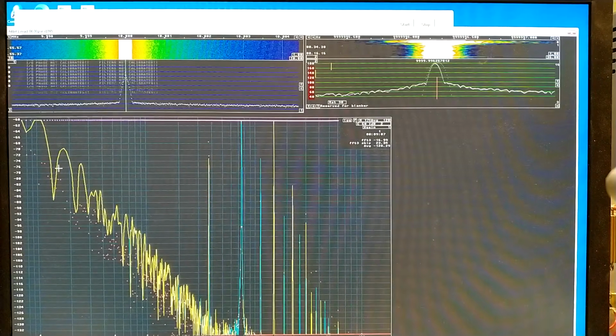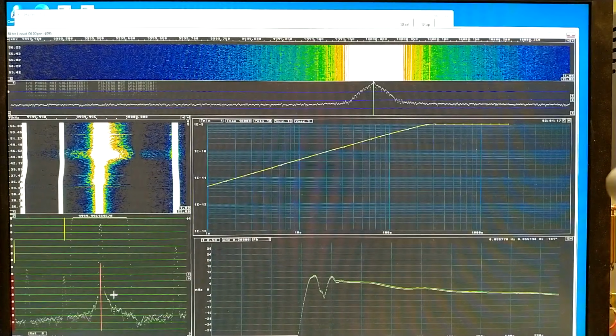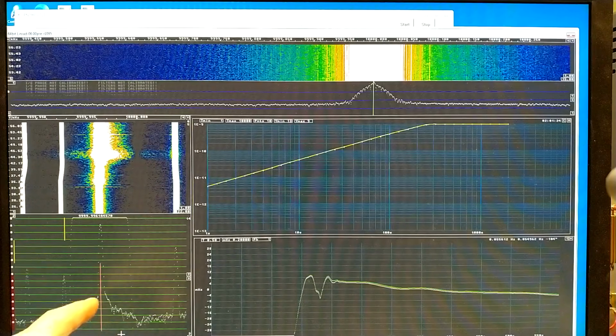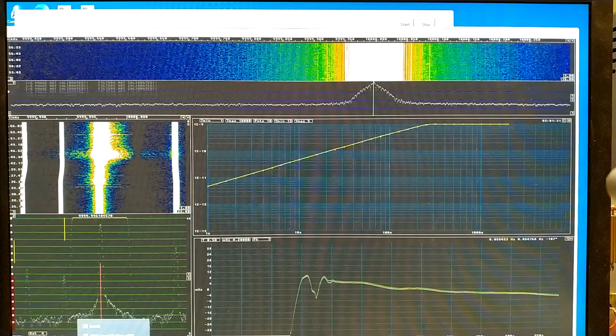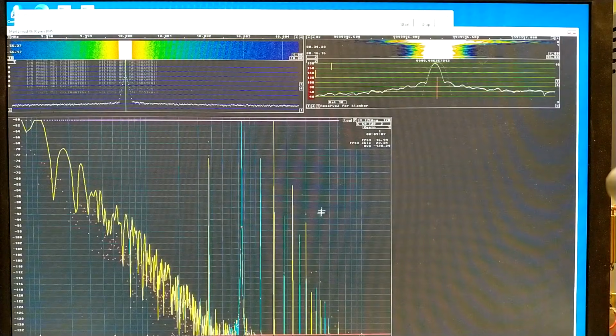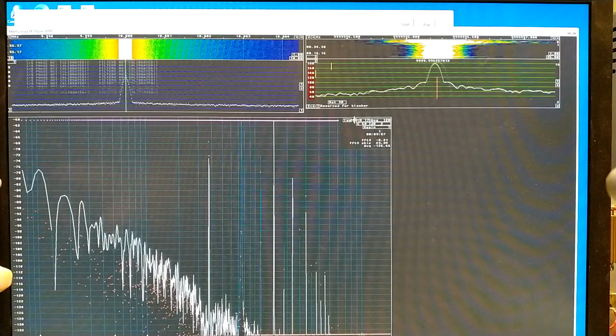And here is now the phase noise, just one transform. But since I had here an asymmetric spectrum, you can see that it is stronger here than here. That implicates there should be an amplitude noise present also. So I look for the amplitude noise, and it is much stronger than normal. It is almost as strong as the phase noise.